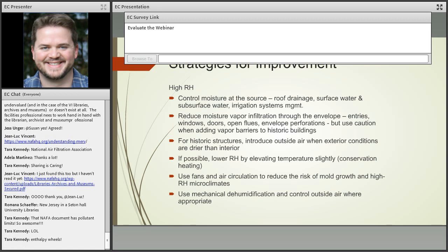I don't want to speak to what the specific environment or the design of the system might be, Tara, but there are certainly applications where if the quantity of dehumidification is relatively minor in terms of what they're trying to achieve, or if it's actually an energy wheel that is being used to transfer heat energy from one part of the process to another, then oftentimes we won't see that superheated reactivation air process.